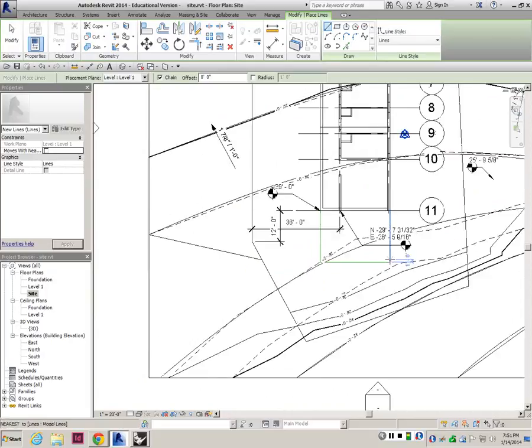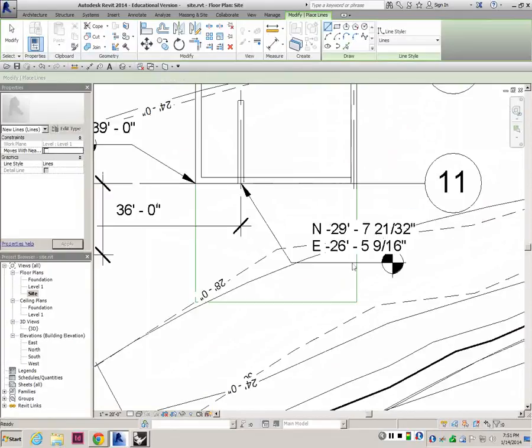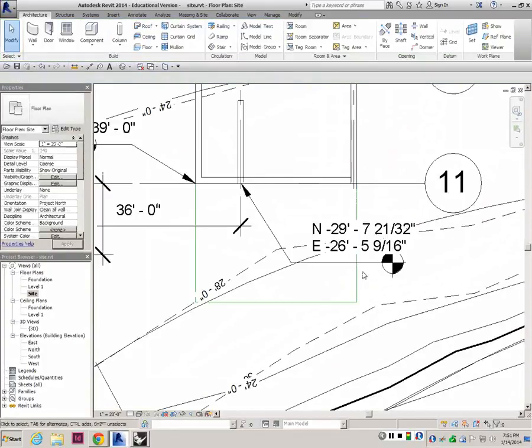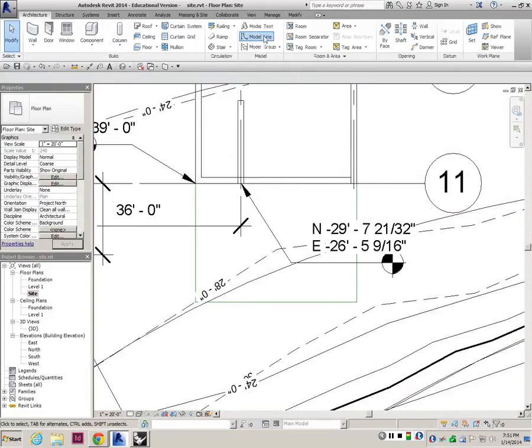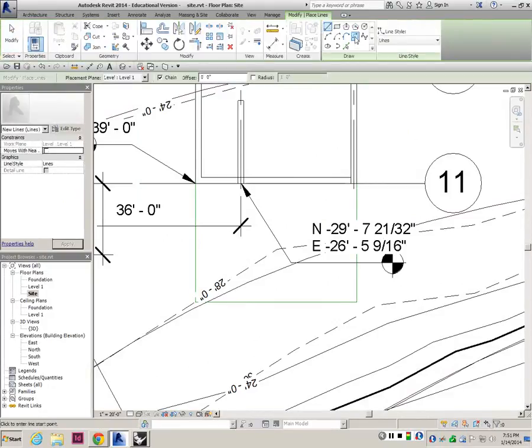Okay, so our road could be merging here, or it could actually come directly from here. So the road could come here and connect to this midpoint, and then the cars could go round about here. And maybe we want to round this up as well, so like fillet it. So if I go to architecture, model line again, this option in draw will be a fillet arc, and that's what we want to do.